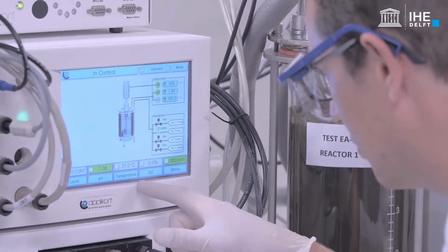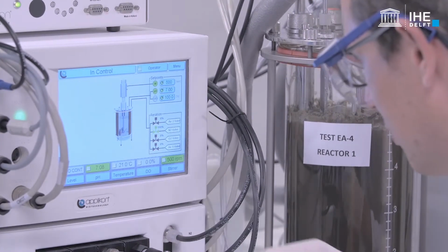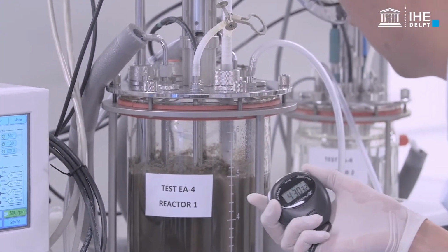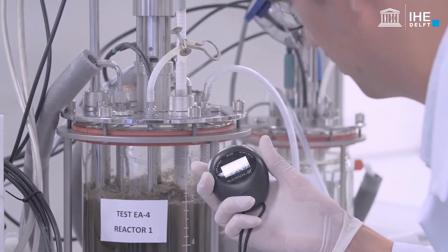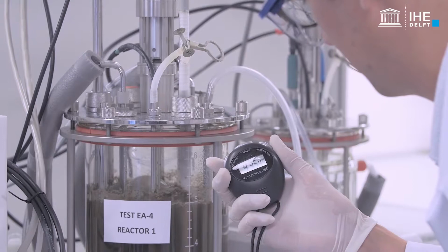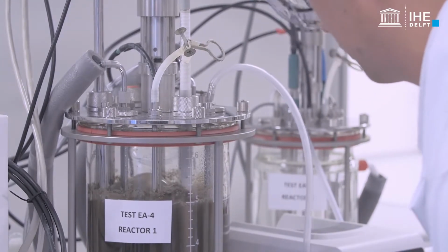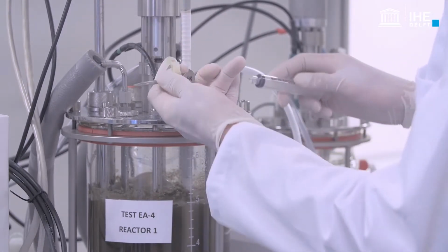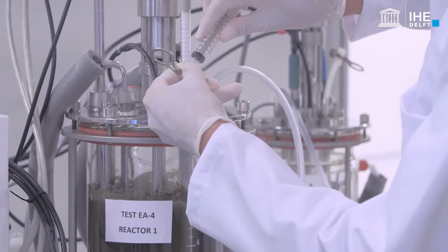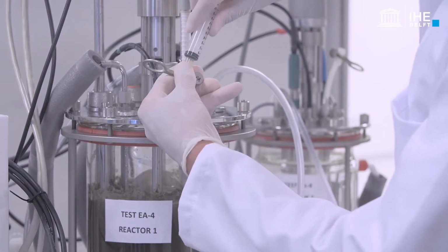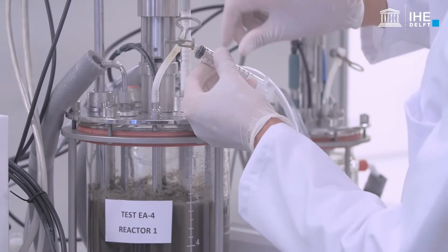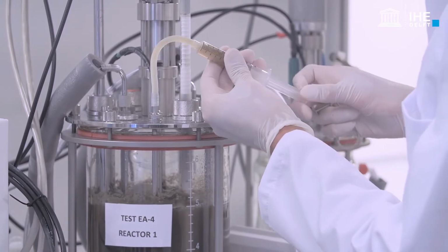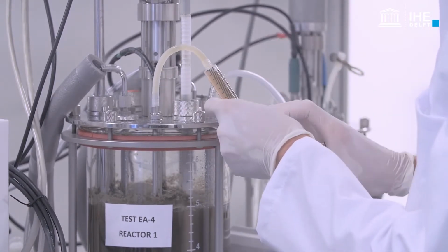After the addition of the carbon source, confirm the stability of the system. Follow the sampling program and start to take the first sample, at least 20 or 30 seconds before the sampling time indicated in the working sheet. This time interval is needed since it can take several seconds to collect and filter the sample. This will help to determine the kinetic rates with precision.